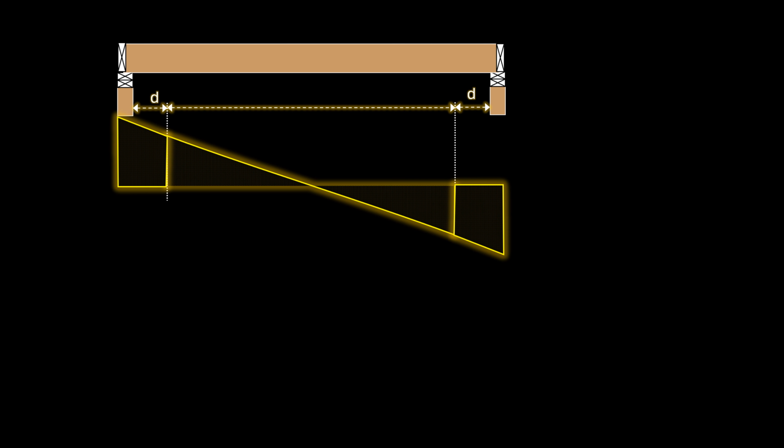Since shear increases as you move towards the supports for a member supporting uniformly distributed load, this allowance in the NDS will effectively reduce the shear force used to design such a member. This reduction is permitted because the loading within the distance equal to the depth of the member will be transferred to the support through bearing and will not contribute to the shear demand in the member. Typically, engineers do not apply this reduction when doing routine shear design calculations for long span members that are less likely to fail in shear.